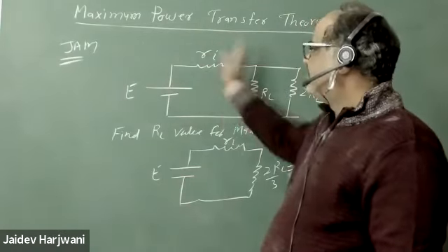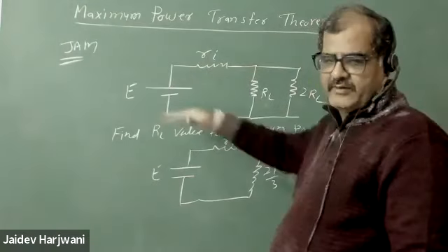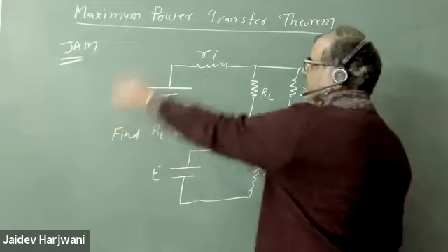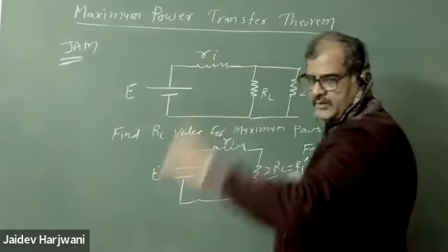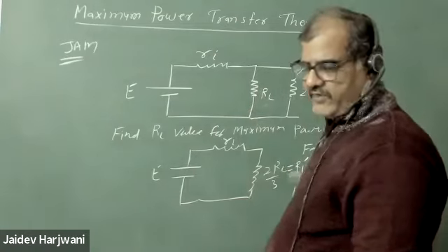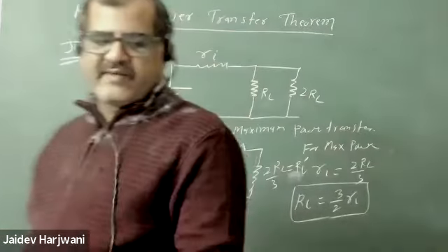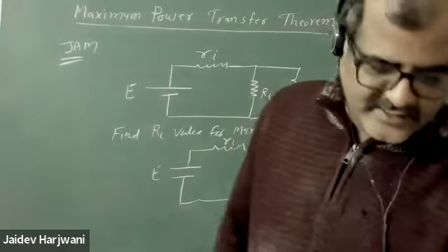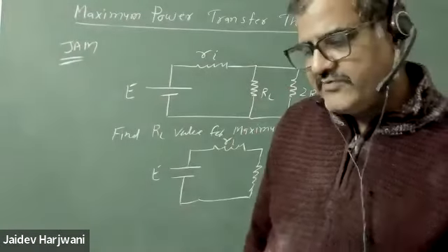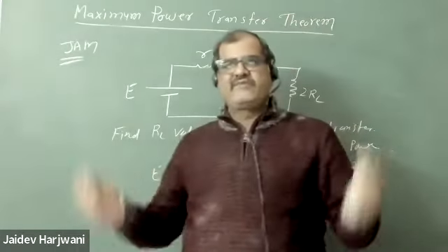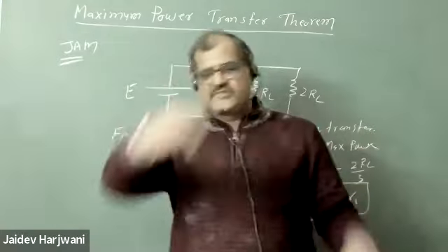So for us, it is like a VThevenin. This source I can consider as a VThevenin. The circuit is given to me. Any circuit it can be, and this resistance that they have given. So say maximum power transfer, what is the value of? Actually, RThevenin you can consider like internal resistance. Internal resistance will be in series with the battery. So whatever RThevenin we are calculating, you can assume that is the internal resistance of the source.